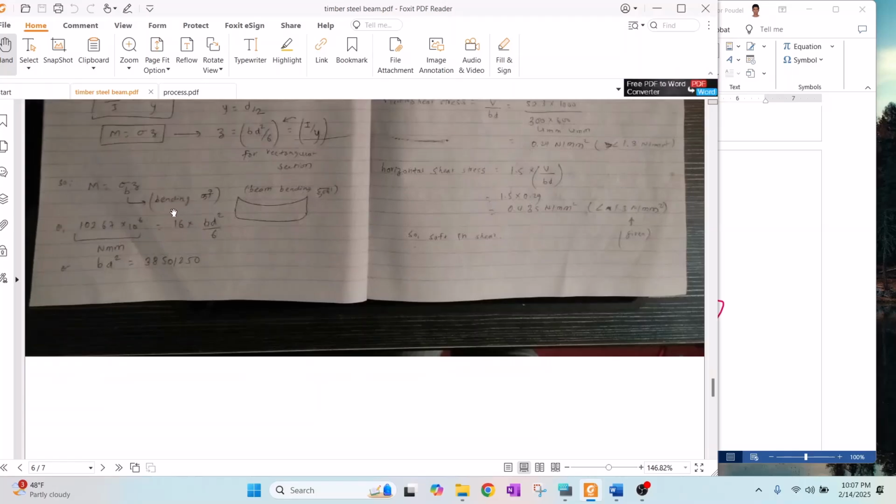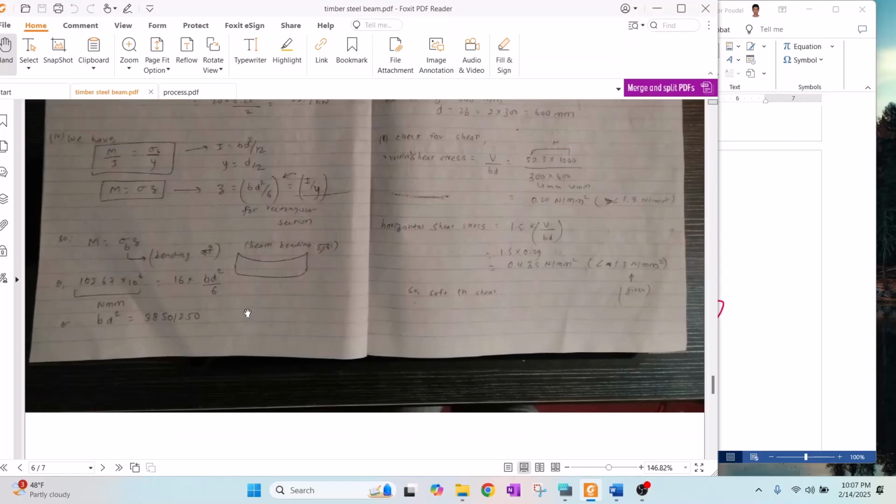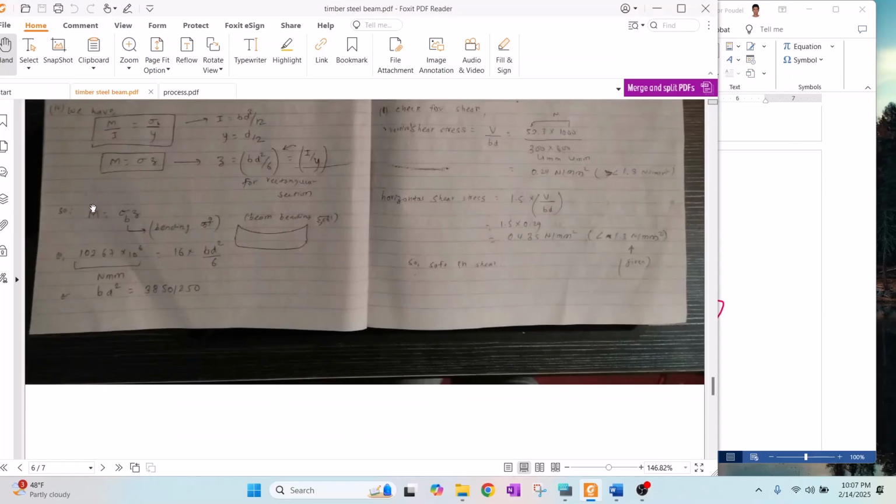In a beam, there is very little chance of axial load, so the beam is designed in flexure only, as a flexural member. So you can use this flexure equation directly here. We have to find the values of b and d, that is the size of the section.